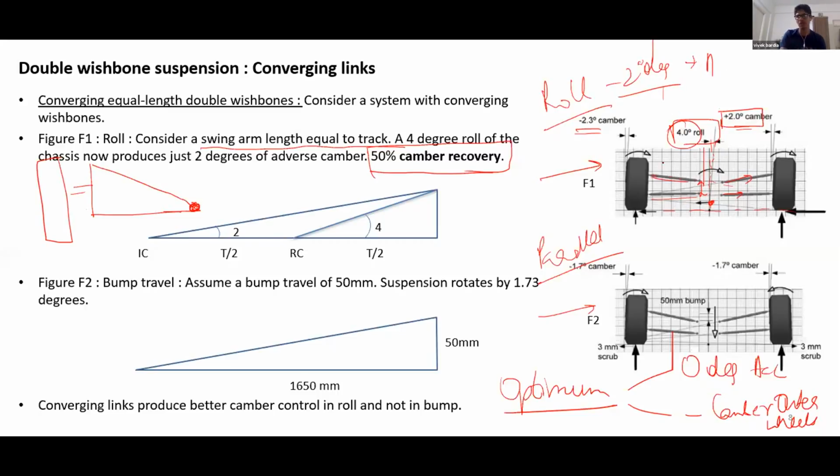So this is assuming you have 4 degrees of roll during peak cornering, right? So you can put in this suspension with minus 2 degrees of static camber so that during cornering, your outer wheels would be perpendicular, maximizing the grip. And during straight line motion, you would have minus 2 degrees of camber, which is slightly better than minus 4 degrees of camber as seen earlier, right?